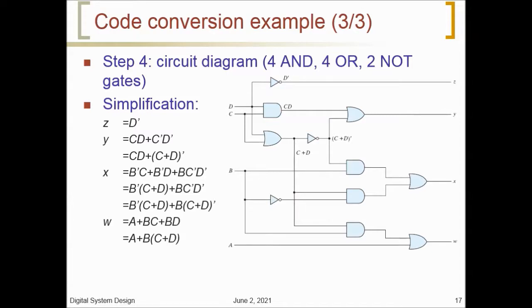If only the normal inputs are available, the first implementation will require inverters for variables B, C, and D, and the second implementation will require inverters for variables B and D. Thus, the three-level logic circuit requires fewer gates, all of which in turn require no more than two inputs.